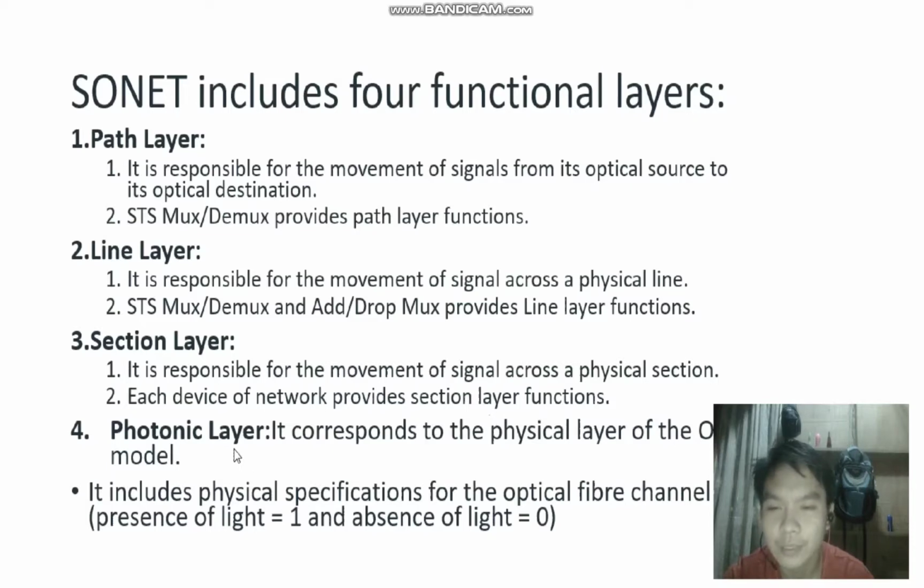Number 4 is the photonic layer. It corresponds to the physical layer of the SONET model. So it includes the physical specifications, optical fiber channel. Presence of light is equal to 1 and the absence of light is equal to 0.